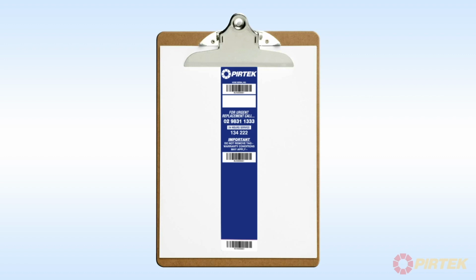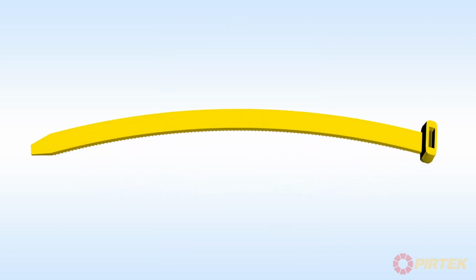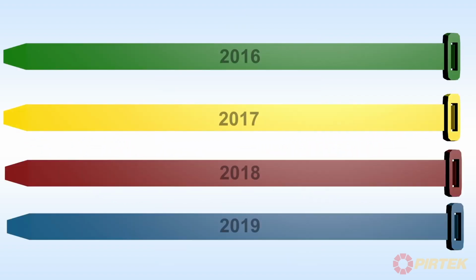It is Pertec policy to attach a service tag to the hose. In Pertec's hose tracking system, the serial number is linked to the hose assembly's unique bill of materials, related manufacturing information, test reports, and service schedules for inspection or replacement. In recent years, for easy identification regarding the age of the hose, coloured zip ties have been used with a different colour for each year.